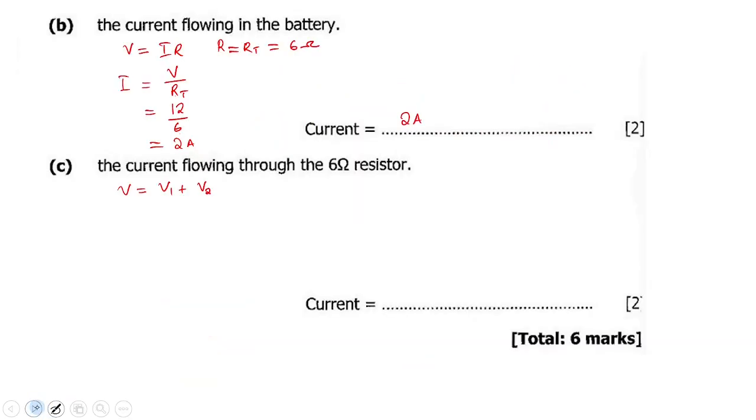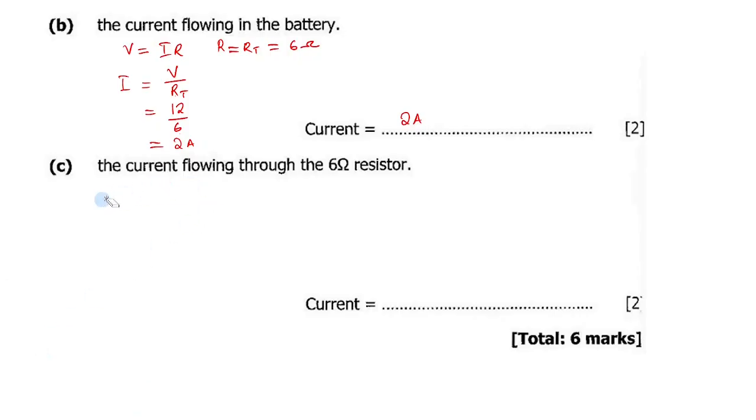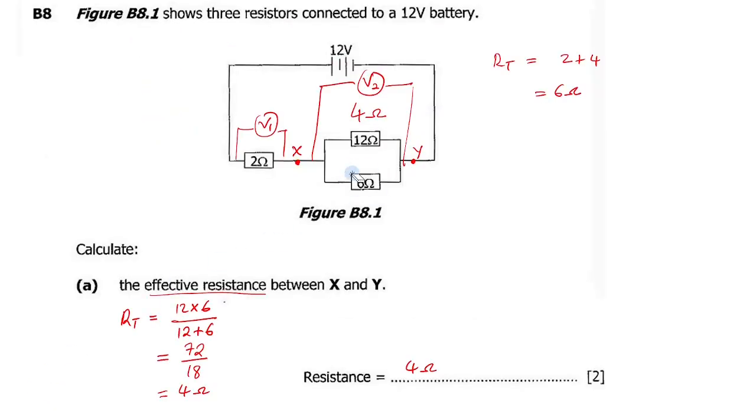So here we find voltage across, and so we are not using this one, which will be a little bit longer on your part, but it is going to work. But I want to shorten the process because I've seen that even here we can still calculate voltage. Knowing the current here, we already found the total resistor, which was 4 ohms, and we know the current that is coming here, it's 2 amps. It's the one crossing here coming this side. So here we know two things: total resistor, and also total current passing there. So we can know voltage.